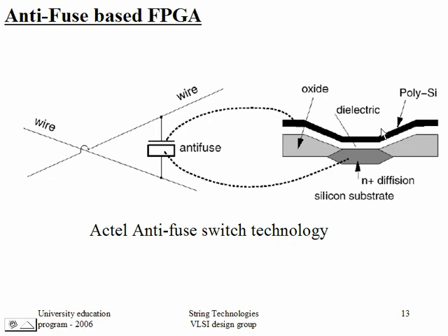So the concept is you have one conductor here and another conductor here. In between there is a dielectric, this white color one. By giving an appropriate electric field, we puncture through the dielectric, so it is programmed. It is similar to a fuse, but by default there is an open circuit, and you can make a closed circuit. But this is also programmable only once. You cannot program several times. Once the dielectric is punctured and the connection is made, that's all. You cannot reverse it.